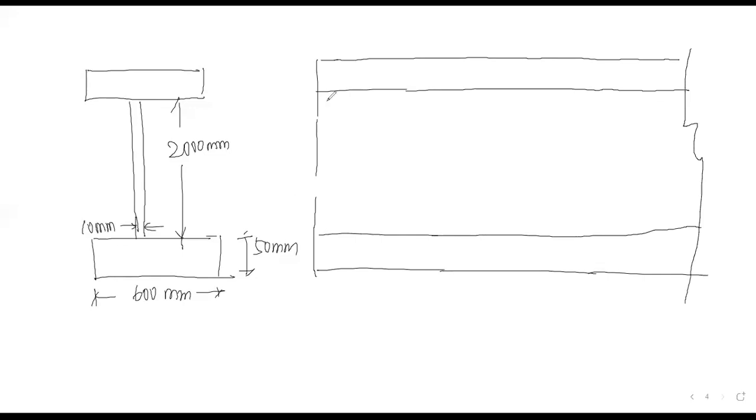So we have designed the end bearing stiffener of size 190 mm by 20 mm by 2000 mm, which is safe to transfer all the forces.